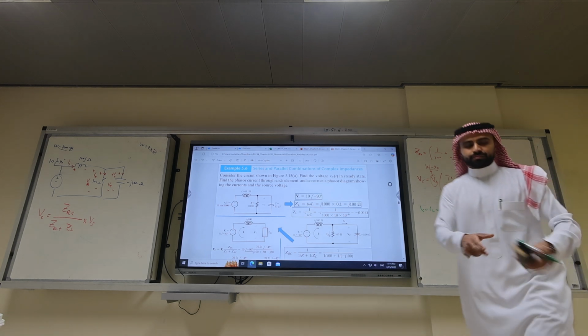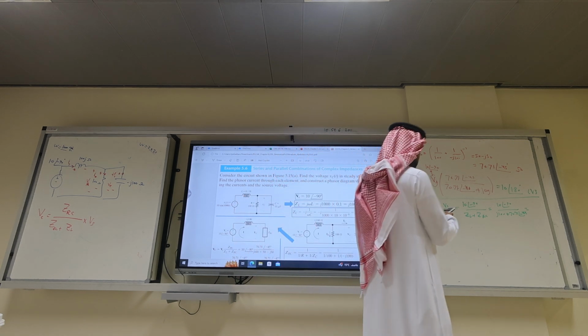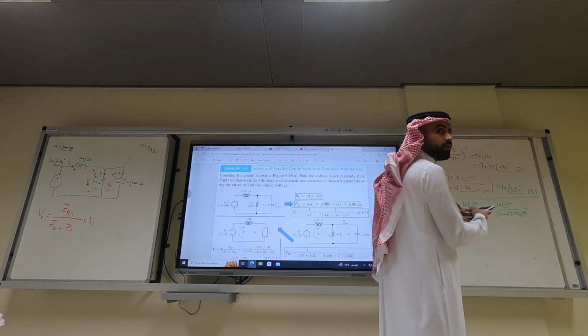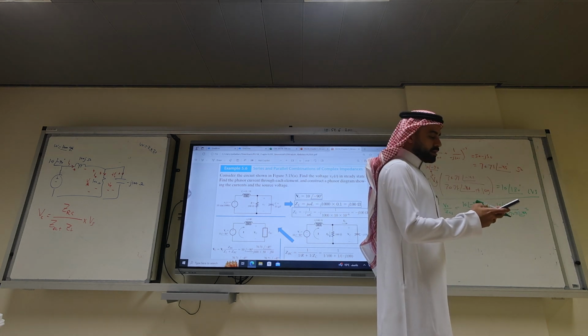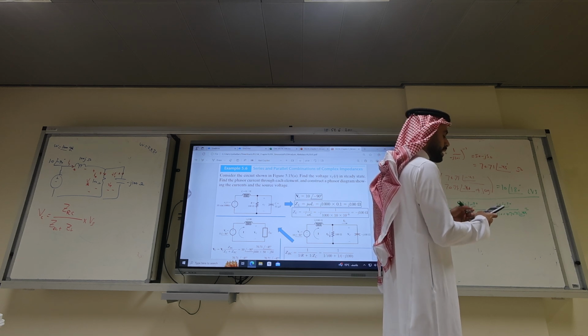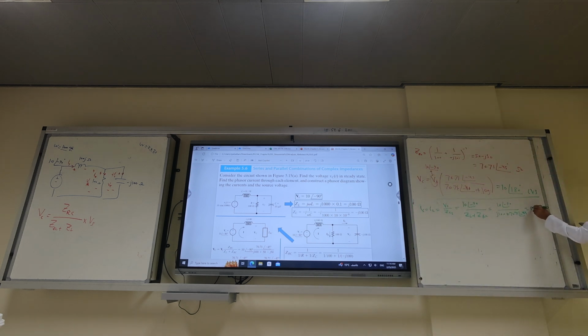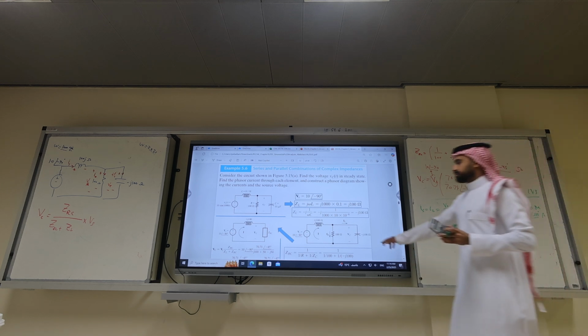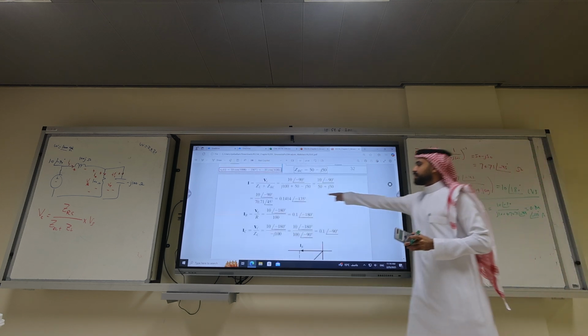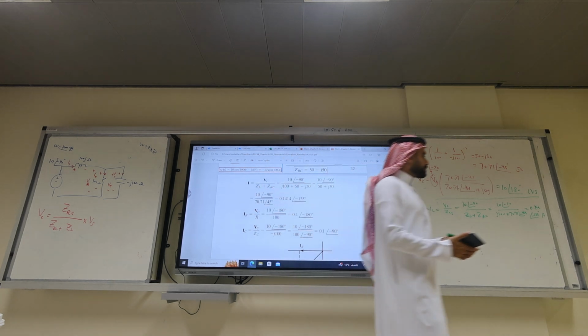What's the final answer? 10 angle minus 90 over J times 100. Do the calculations. What did you calculate? I see, Muhammad, you're wasting a learning opportunity during the class. Let me know if it's 0.14 angle minus 135 amps. It's the same? Yes. That is I. Here I call it IS, you can call it IL, it doesn't matter.